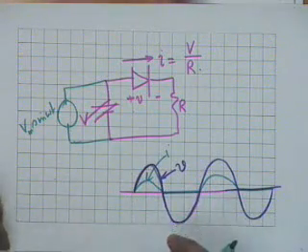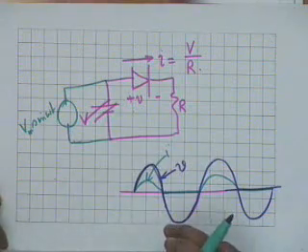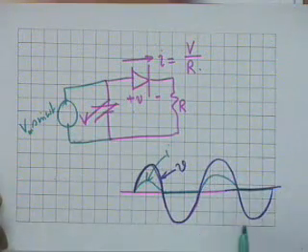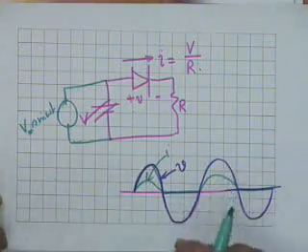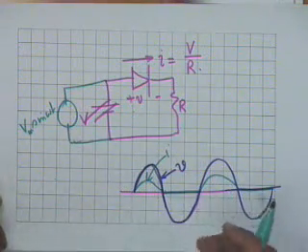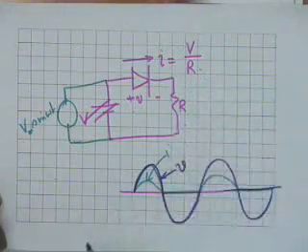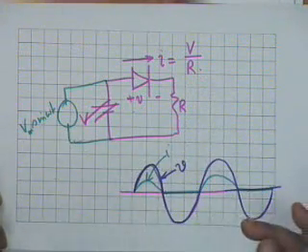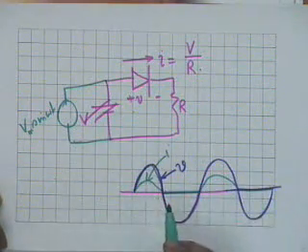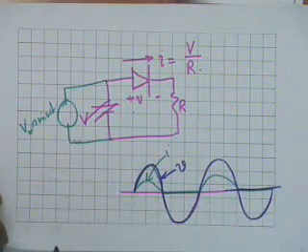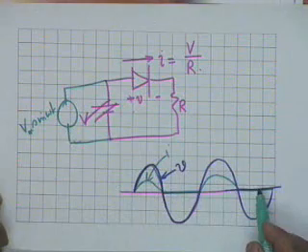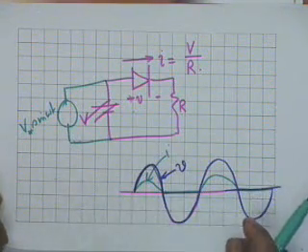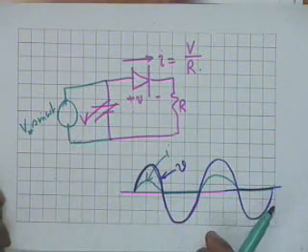Therefore, a bidirectional voltage, a voltage which could be positive as well as negative, is being converted into a unidirectional current. And by dropping the current in a resistance, you are converting this to a unidirectional voltage. However, this voltage is not constant. It is pulsating, it varies. The average value of this obviously is a DC voltage.